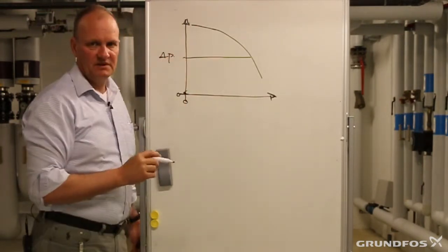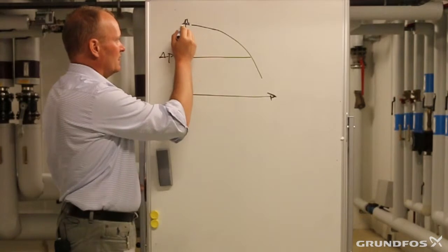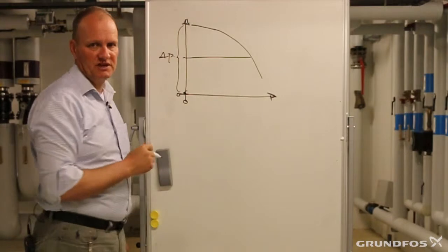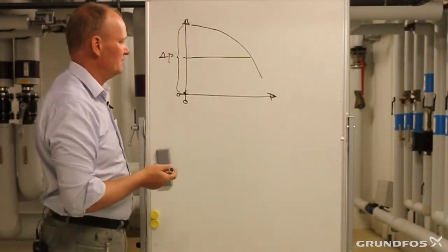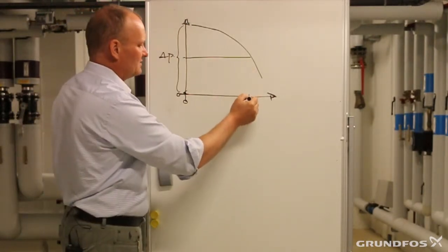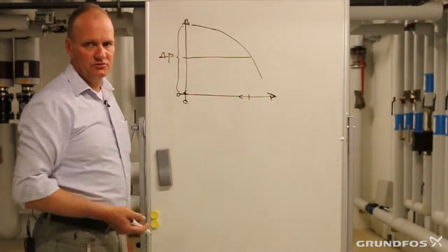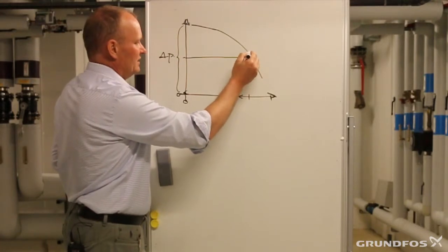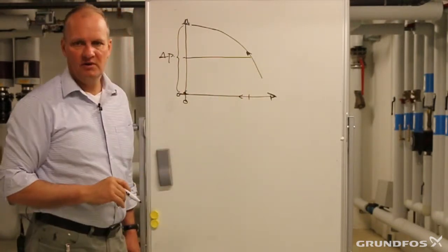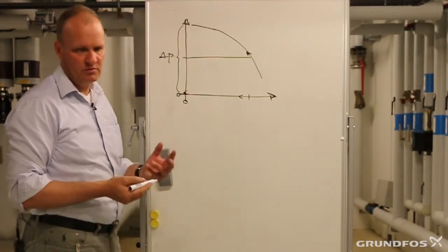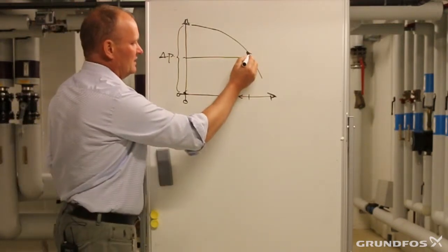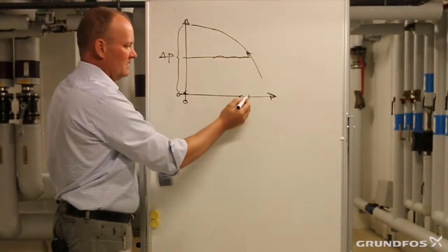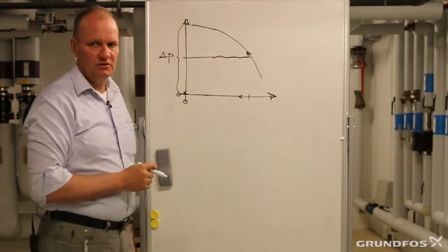Remember that the pump is constantly monitoring what am I delivering in difference from the suction side and to the discharge side of the pump. So when the valves are closing due to these dynamic valves, instead of going up and creating more pressure as what a normal pump would do, a non-controlled pump, then an e-pump goes down and follows this line at the same speed as the flow is going down.